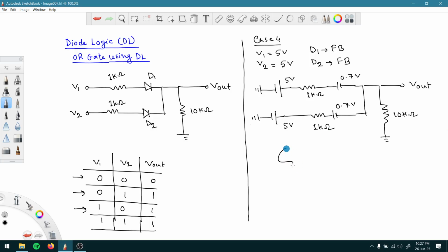So if we have a big circuit like that, and we have one ground coming from here, maybe another ground coming from here, another ground coming from here, and different things can be here. We are not thinking about those things, but multiple grounds are coming out of the circuit. Like here we have 3 different grounds. These can be considered as shorted, connected together, because they are at the same voltage level, or all of them can be considered as the same node. So the same concept can be applied here also.